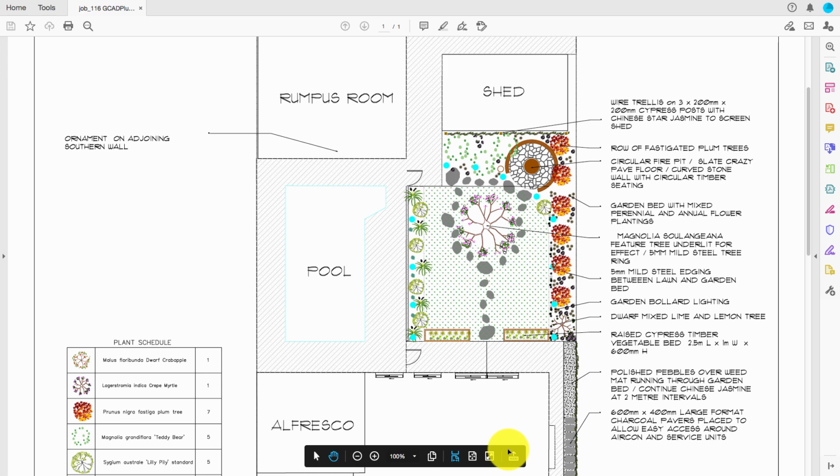So here we are in Acrobat Reader looking at the PDF that's been generated using 2400 by 2400 high resolution printing, and we're looking at that little area where there was a solid filled garden bed, and transparency was applied. We don't see it, so we miss out on transparency once we get to print, but we gain one advantage where we can print to an accurate scale.